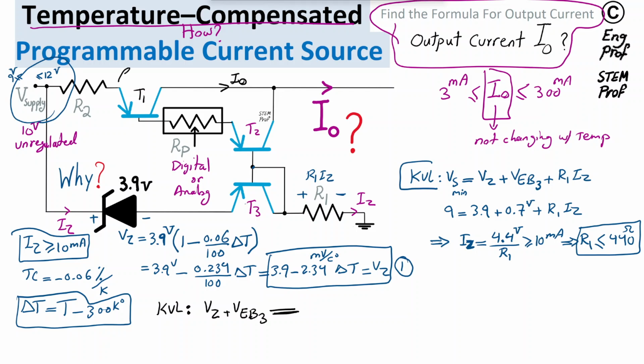So the beta, or the current gain for this transistor, which is the collector current divided by base current, is very safe to assume it's at least 50 for the transistor. So this is T1. Therefore, with beta, the base current for this PNP transistor is the collector current or emitter current divided by 50 at least, which is the same as emitter for T2, which means is the same as this one, is roughly, or at most, I out divided by 50.